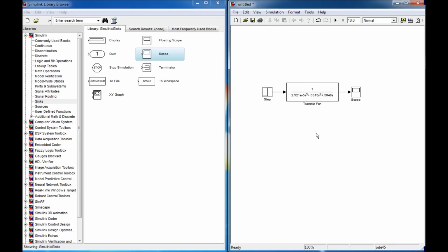So now let's model a proportional control system using Simulink. And what our proportional control system is going to do is take our output position, and set our input voltage to the motor depending on the error in our signal, which will be some reference minus whatever our current output is. So I'm going to click on these two lines here and delete them. Let's move that transfer function over. So to do that, we're going to need a couple more math blocks.